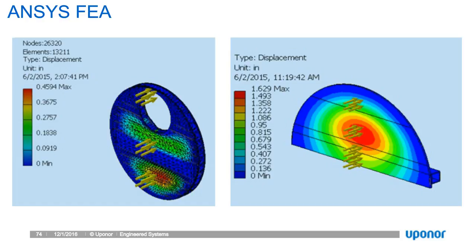If that deflection exceeds allowable tolerance in the range of L over 1,000, we can reinforce the annular space in the system, or we can provide additional external reinforcing. As you can see on the bottom right of photo right, we actually ran a profile, and we can put steel inside that if necessary to improve the strength of the system when it's required.